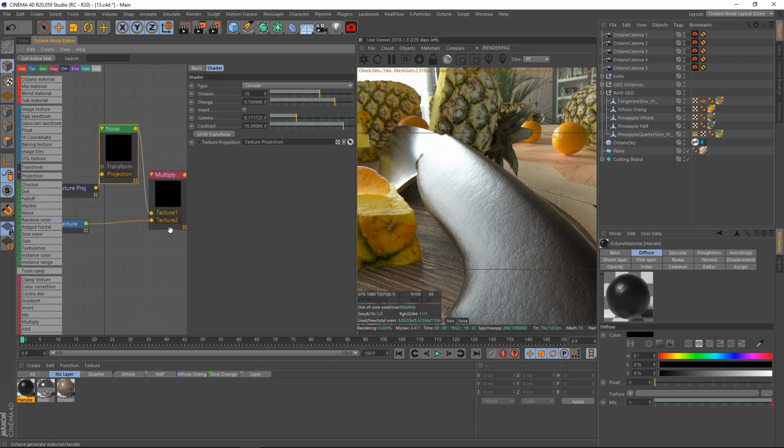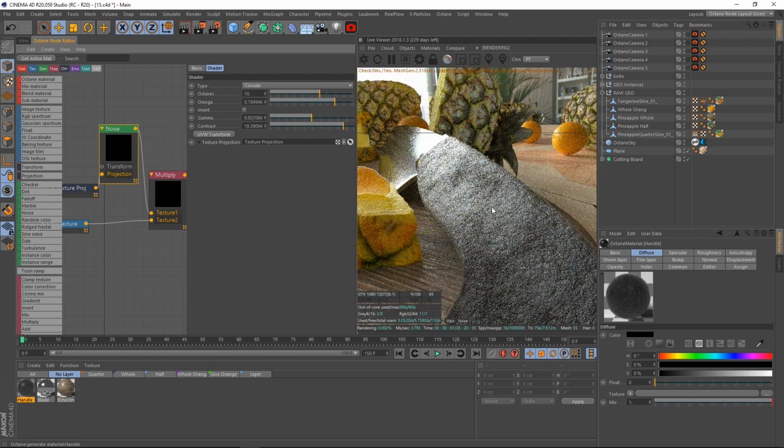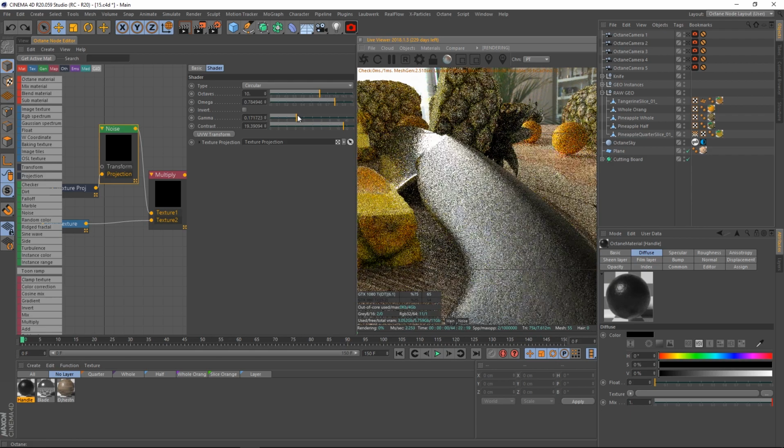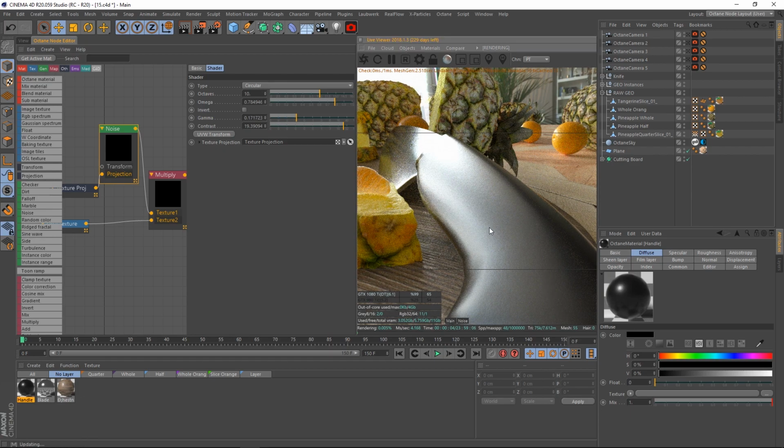All I did was I took a noise, used circular noise, octaves of 10, dragged that omega up again, and played with my gamma here to increase and decrease the contrast. If I go too much this way, it's just far too much of that showing through. And if I go the opposite direction, we flatten it all off to basically a perfect white or black, and then we lose a bunch of detail. So a gamma adjustment was necessary to adjust the blacks and white points in that, and then the contrast up just to bring in a little bit more detail.